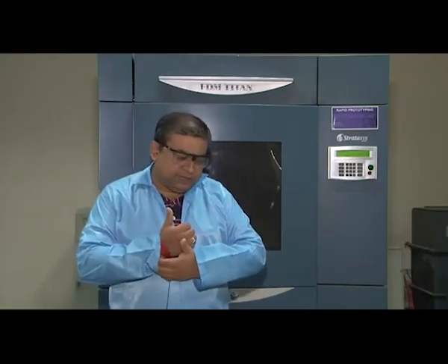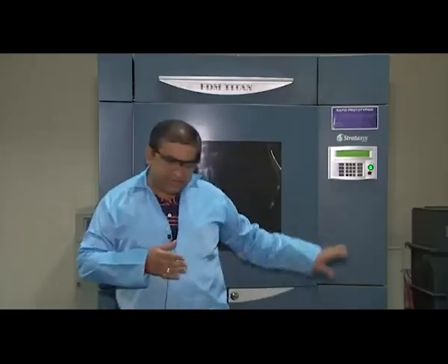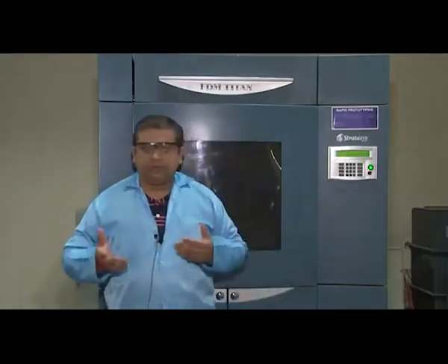Okay, so the advantage behind 3D printing, this area is also known as layered manufacturing because you are manufacturing layer by layer. And the advantage behind such manufacturing processes is typically in terms of the saving of excess material that you otherwise incur in other contact machining processes, where there is a lot of waste generated in the form of chips, or even in other forming processes or associated, let's say, casting processes, which are primary manufacturing processes. There is always a tendency of formulating a layer which is eventually removed.